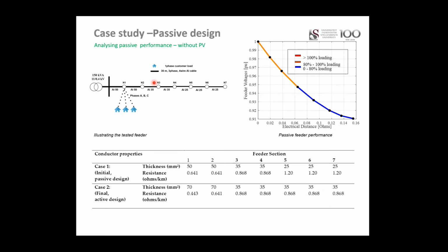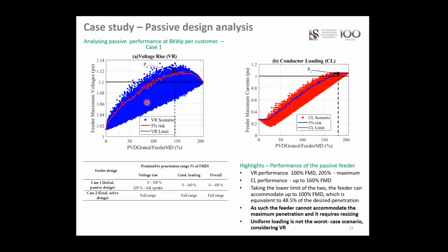Okay, so probably I should explain from this, then I shall go on to the full uptake side. As a distribution network planner or operator, you want to design a system that can meet a certain threshold. So if you say that your planning is supposed to meet 100 kilowatt peak, then it's distributed in such a way that each customer has a certain threshold, such that your full uptake is at 100. But that's not a prerogative. It's got nothing to do with your feeder maximum demand.